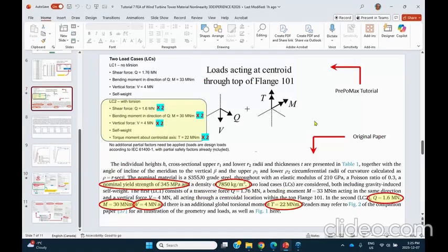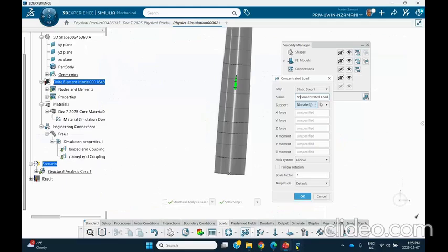In fact, in Wagner's YouTube, he's using 10 times that, but it really doesn't matter. It's used because after all, I'm not going to let it go all the way to the end. So I'll use negative 8 meganewtons. So we go here. I called it V. In the negative y direction, minus 8. Make sure you put e to the 6, right? E to the 6.